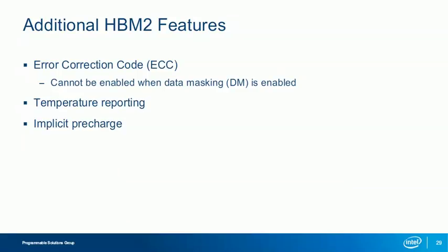HBM2 supports ECC, which is also supported in DDR4. However, HBM2 ECC cannot be enabled when DM is enabled, since the ECC signaling is shared with the DM signal. HBM2 also supports 2 additional unique features, temperature reporting and implicit precharge.